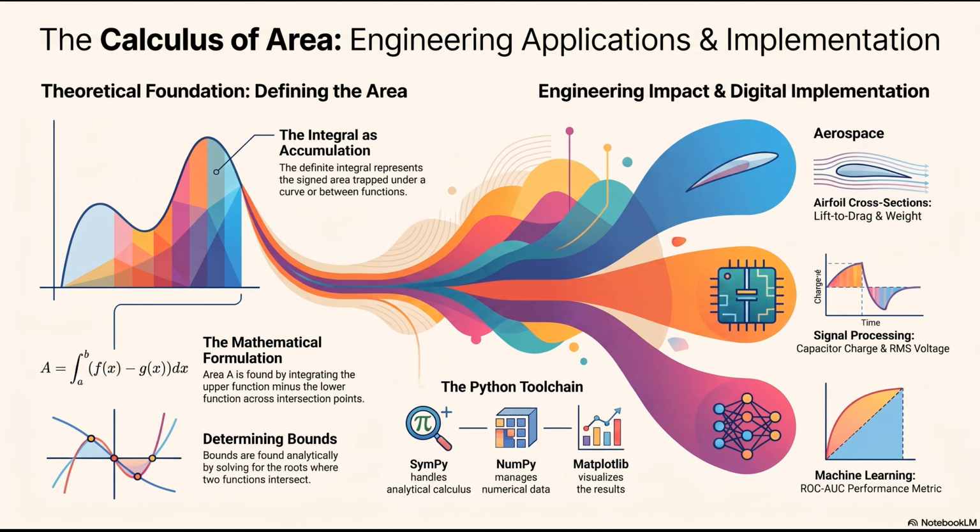So I understand that the integral calculates the physical area inside that loop, but the document says that area equals work, or measurable energy. How does an area on a graph suddenly become mechanical energy? It's all about the units. Let's break down the units, because this is where the physics gets truly beautiful. Pressure is defined as force divided by area. Force over area. And volume is defined as area multiplied by distance. So when you calculate the integral, you are mathematically multiplying the y-axis by the x-axis. Which means multiplying pressure times volume.